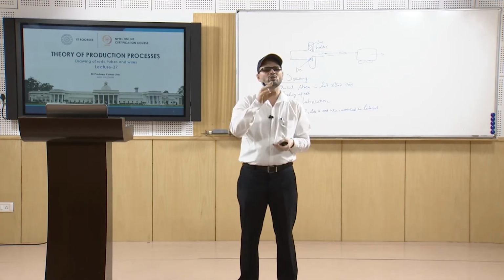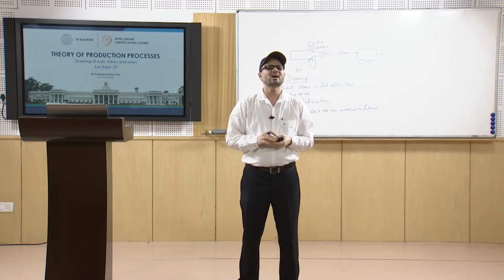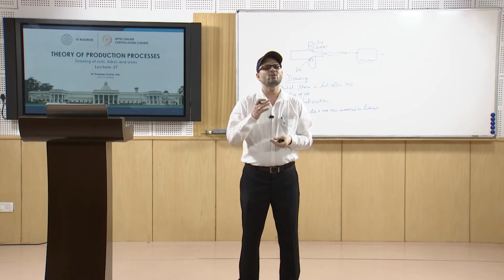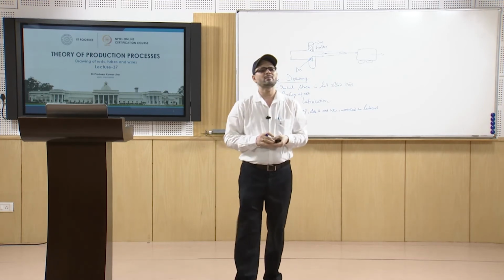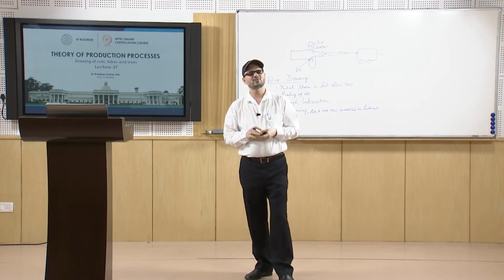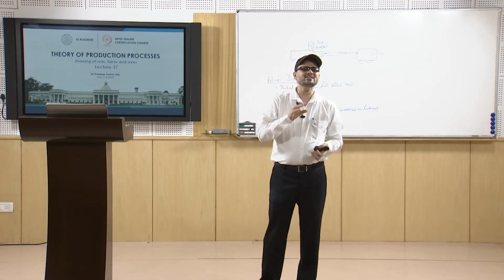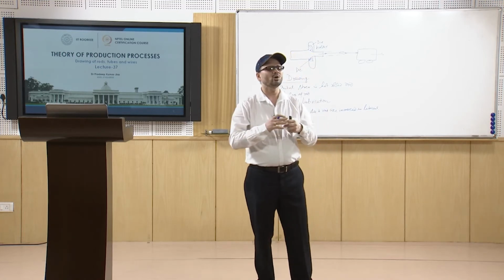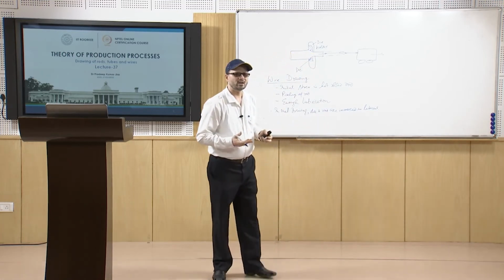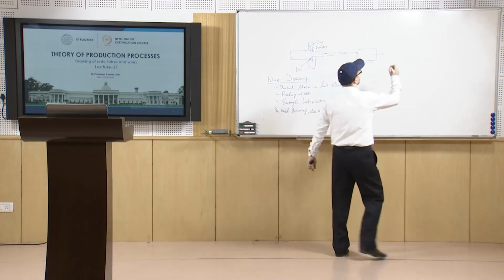They are basically hollow cylinders or tubes which are often cold finished by drawing to obtain closer dimensional tolerances, better surface finish and increased mechanical properties. In this case when you do not use anything, then we call it tube sinking.